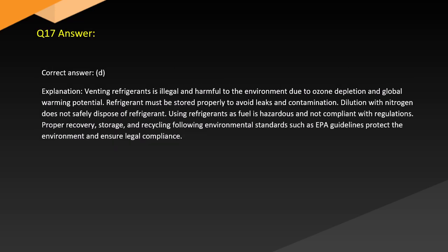Answer. Correct answer. D. Explanation. Venting refrigerants is illegal and harmful to the environment due to ozone depletion and global warming potential. Refrigerant must be stored properly to avoid leaks and contamination. Dilution with nitrogen does not safely dispose of refrigerant. Using refrigerants as fuel is hazardous and not compliant with regulations. Proper recovery, storage, and recycling following environmental standards such as EPA guidelines protect the environment and ensure legal compliance.